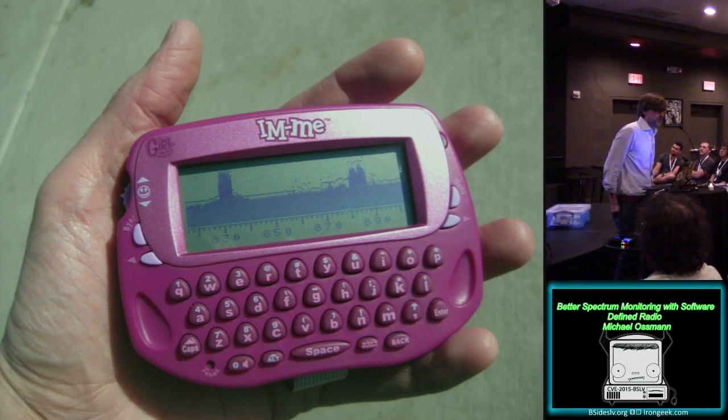The IM I was introduced to by Travis Goodspeed, and he taught me how to program it, and then I said, hey, I could build a spectrum analyzer out of this. So I wrote software to be a spectrum analyzer, and what it does is it tunes its little radio chip to one frequency, takes a measurement of the radio energy, and then plots one column of pixels to the screen. Then it shifts over to the next frequency, tunes the radio, takes a measurement of the energy, and plots a column to the screen, and so forth. It sweeps across this 130 pixel display many times per second, 20-some times per second, something like that.